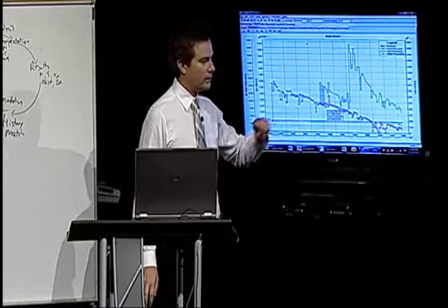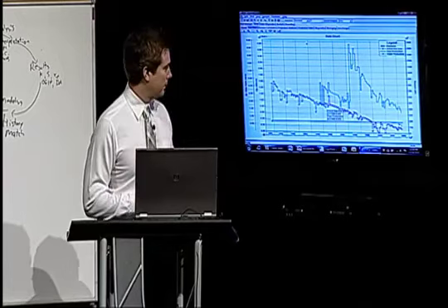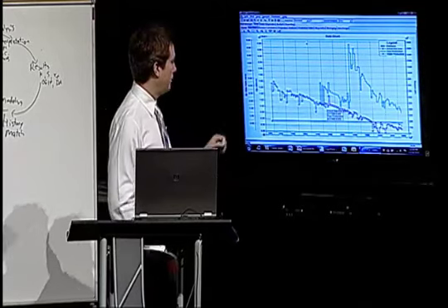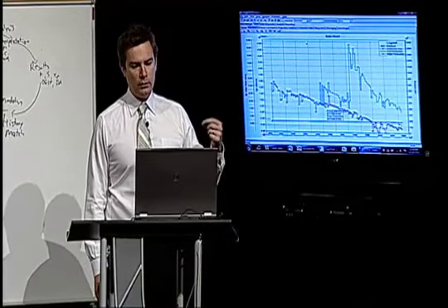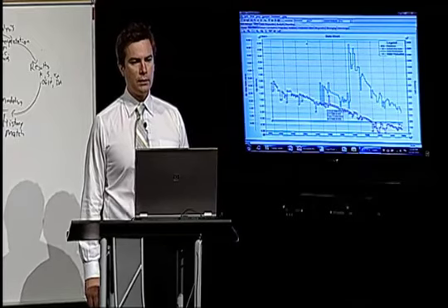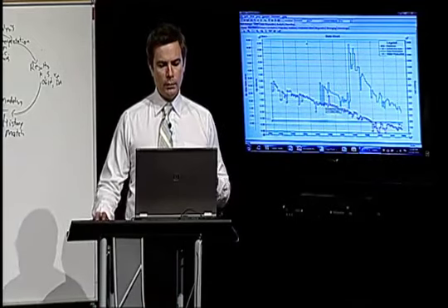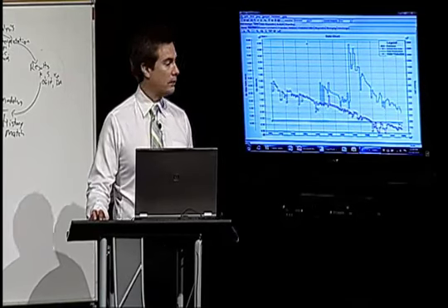Normally, this would be a little bit dangerous because I've just finished telling you, as part of several different discussions, that flowing pressures are very important. But in this case, we knew that the wells were operated at very high drawdown, and we knew roughly what the line pressure was. So we were able to predict the flowing pressures in this situation. In most cases, you'd want to have access to all those flowing pressures to get a more accurate interpretation.